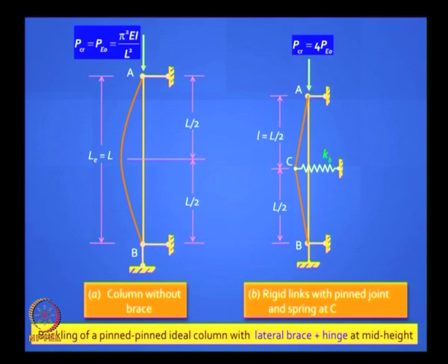If I put a hinge there, then definitely it is going to buckle like this. Can I find out the minimum value of KB needed from this picture? How do I get it? Just equilibrium, you're right. You will get a reaction there. If I take the free body, which is 2P phi, when I solve that equation, that's the force in my spring. So if I have a spring with a capacity greater than that, it will not happen. So that's how I get KB.